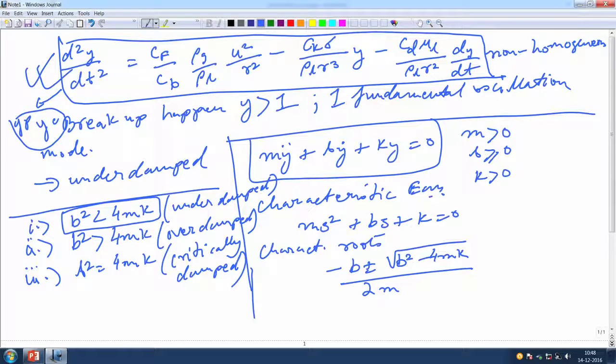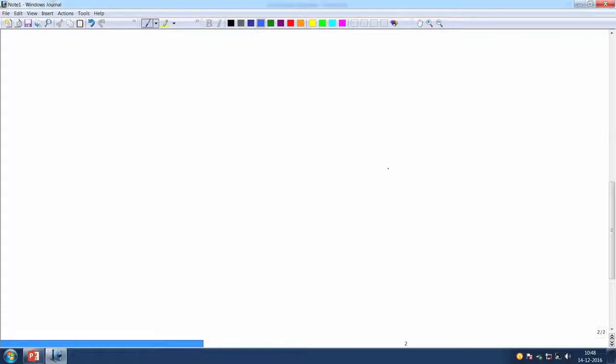It will be equivalent to a free vibration equation minus this particular term. If you solve the free vibration equation minus this term, which is basically removing the forcing, you will get the complementary solution. That is what you know from your vibrations already. So the complementary solution is nothing but the same as free oscillation. In this case it is underdamped.